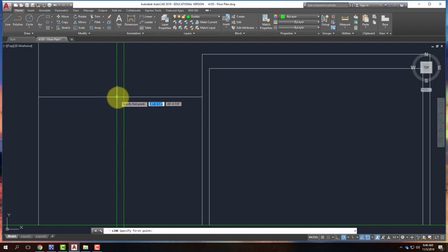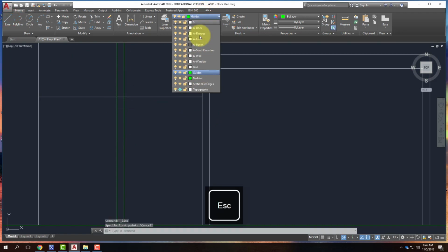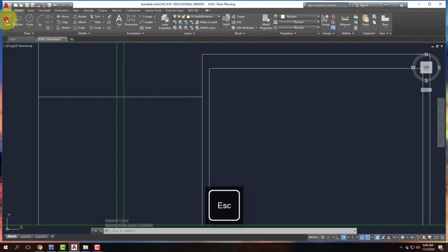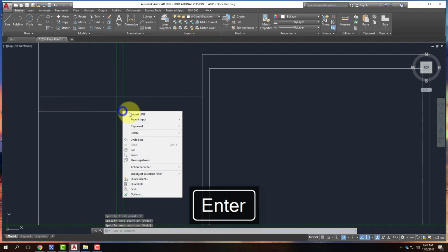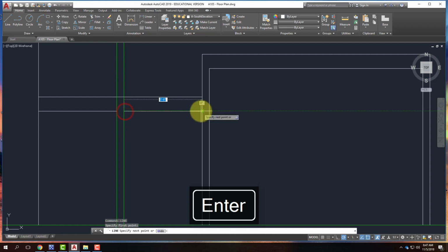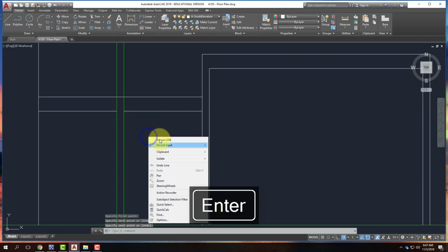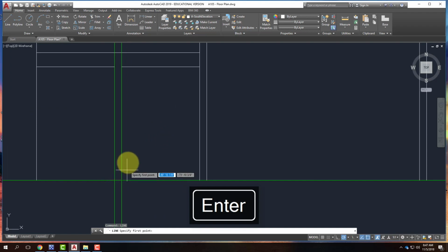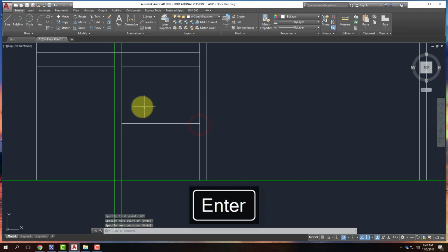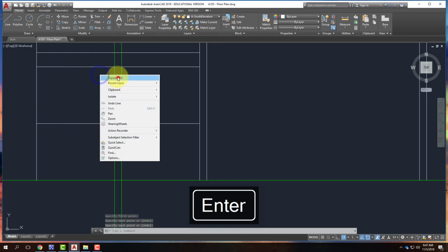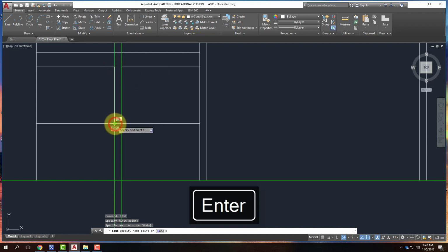So in this case, I'm going to go down. Let me switch to my south elevation. I'll go down by 1 foot. And there's one window. There's the other window. And these are in the bathroom, so I'll do them at 48 inches as well. Now, why there would be a full window in the shower, I'm not quite sure, but I drew it that way, so it is what it is.